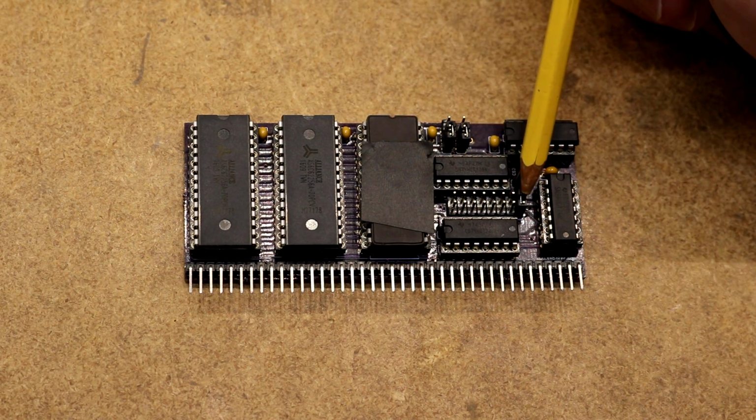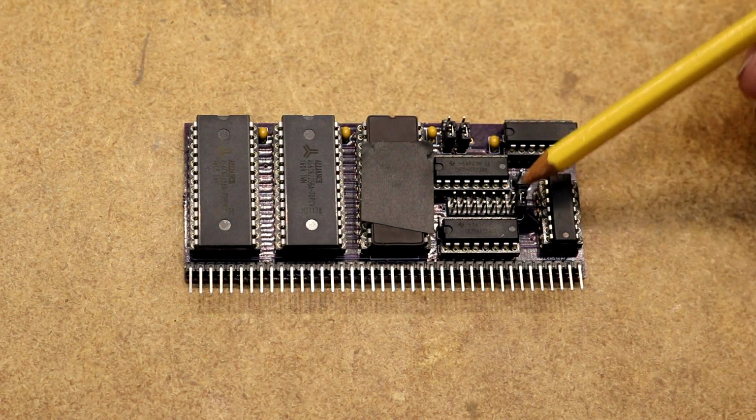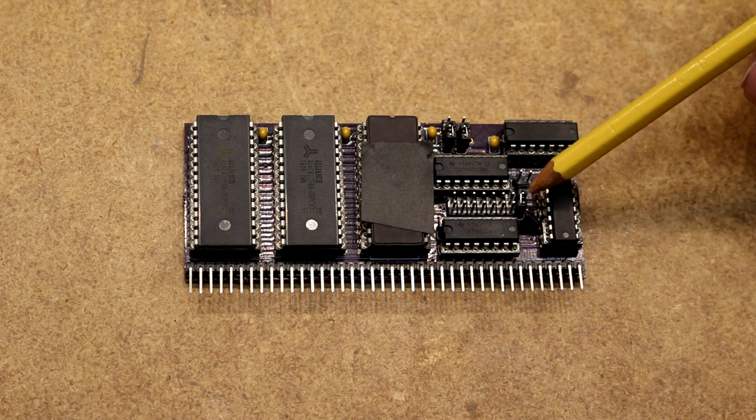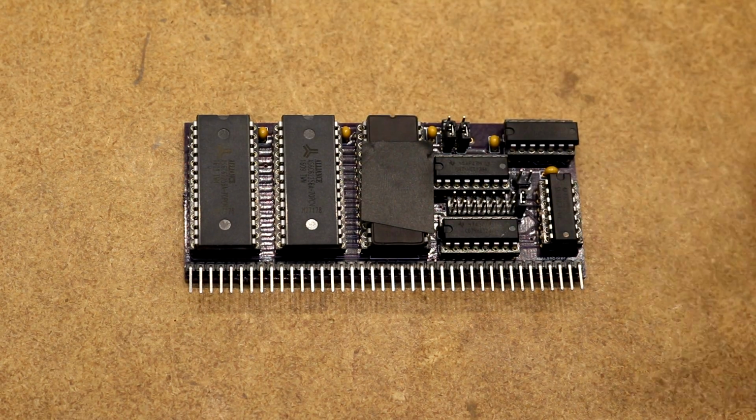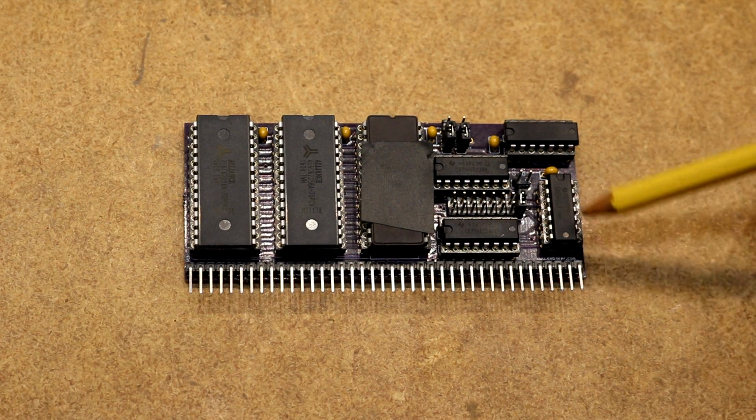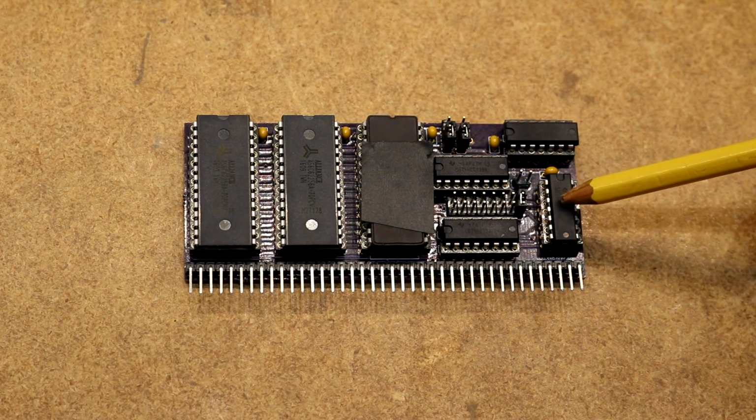This header selects which address on the 3 to 8 decoder is used, and the address that I have enabled is 38 hex. Here's the 74HCT139, that's the 2 to 4 decoder that drives the chip selects.